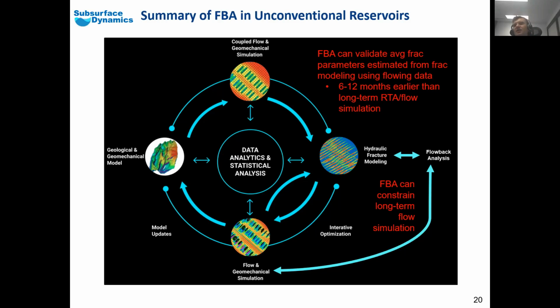The key benefit is that flowback data analysis can validate average frac parameters estimated from frac modeling, and we don't need to wait for the long-term production data. We can answer the question of how efficient our fracs were within a couple of days after the flowback was started and the data was acquired.